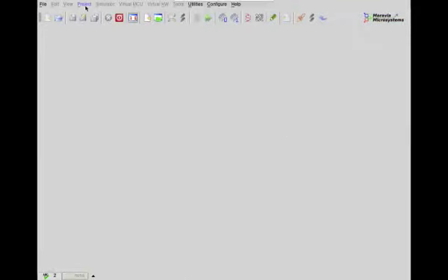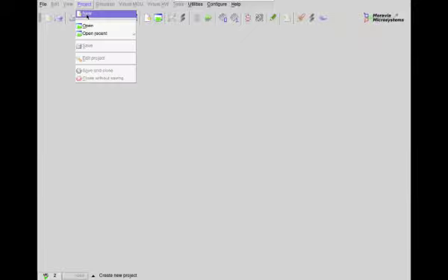Now today we will see MCU IDE 8051. It's a very good simulator in which we can run the program, we can simulate the program, we can simulate interface, a virtual hardware also. So it's a very good virtual platform to study the microcontroller and its application. So first step is go to the project and select new.